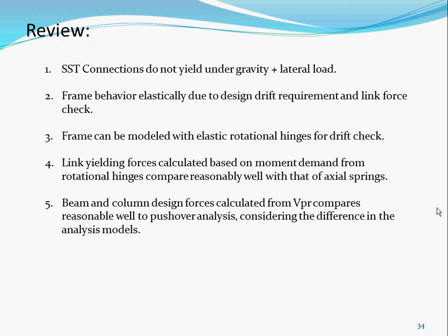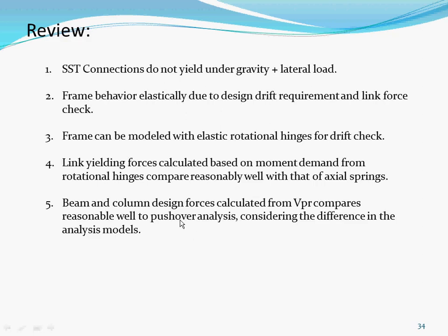Beam and column force is calculated for VPR reasonably well. I'll go into the pushover analysis a little bit, on why we do that if we want to do that. For design it's not required. For a lot of retrofits here in the Bay Area and Southern California, there's a new FEMA 807 code that requires you to tell them how your frame is actually behaving. If they require that, then we have to do the pushover analysis to tell them how the frame behaves. Instead of just giving the elastic portion, they want to know how it behaves until it breaks, until it's 5%.